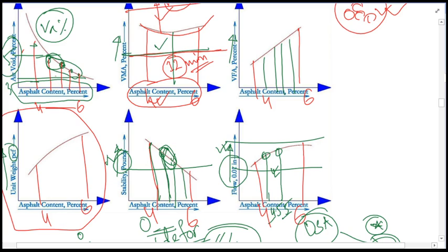And if you find that no asphalt content is satisfying, that any one of these graphs is going out of the specified or desired range, then you will have to change the gradation of this aggregate. Using this aggregate, you cannot satisfy this mix design. Rather, we'll have to choose different grades. Then we'll have to try this again and finalize whether this aggregate sample and the particular asphalt content are okay for this mix design or not, and that's how you will have to proceed.